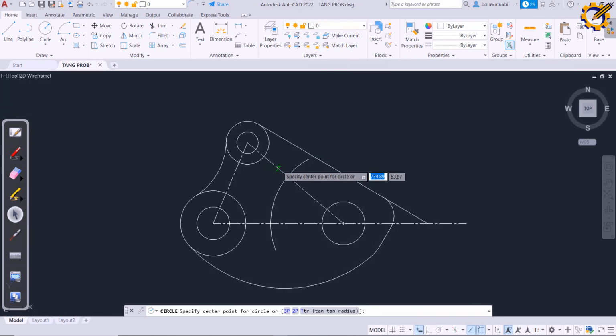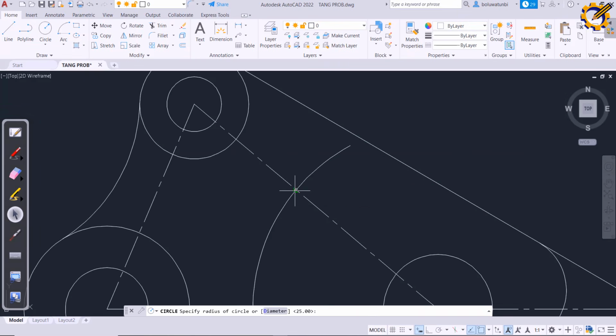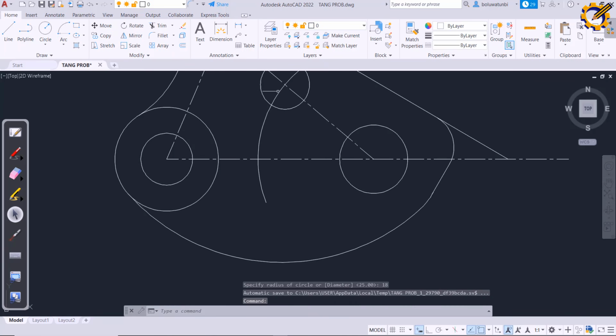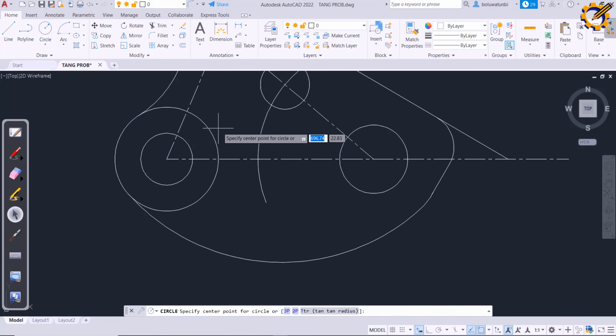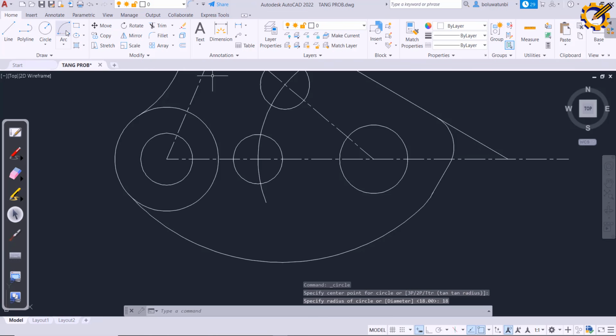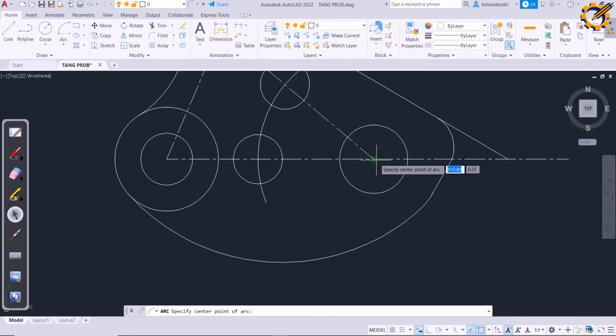So I'm going to come here and draw radius 18, enter, and still come here, and from here radius 18, enter.